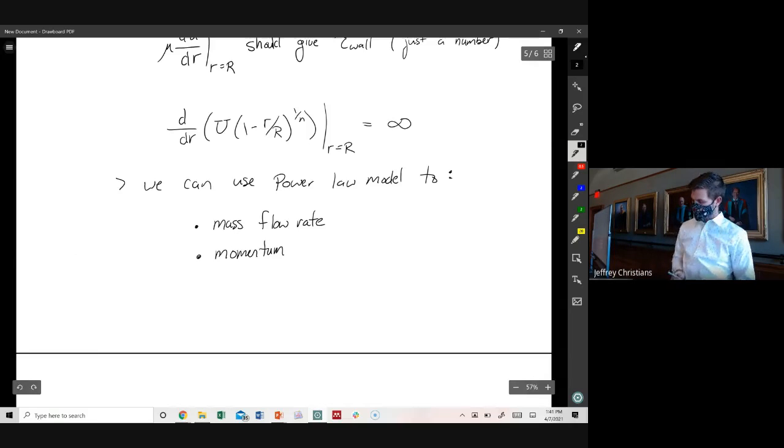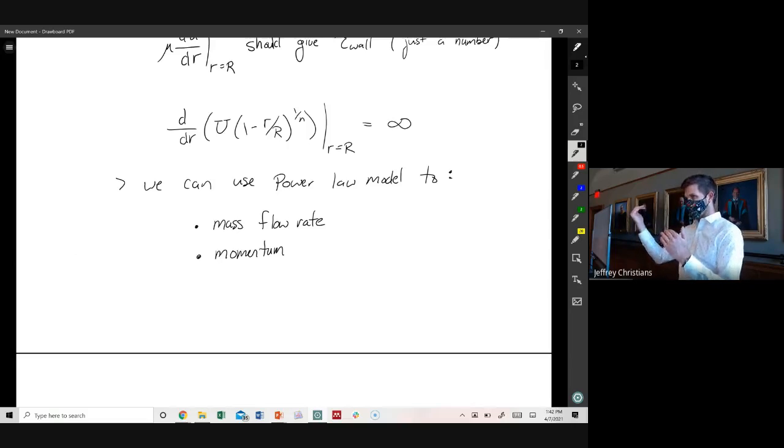We could figure out momentum. If we had something with laminar flow, we know the velocity profile and we can do our integral from the center, right? Remember Reynolds transport theorem? Most of the time we said, let's assume a uniform velocity, then we don't have to do the integral. We could use a model like this to get more sophisticated than what we were doing before. And we could figure out what is the momentum given the velocity profile. We get a fairly accurate answer.